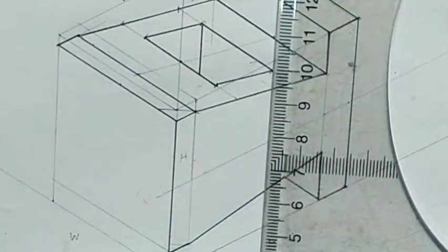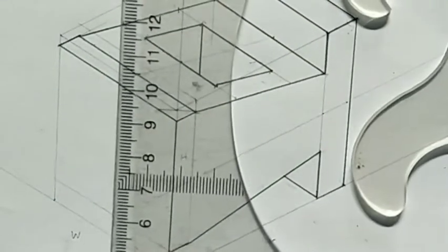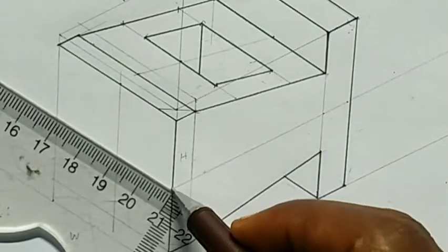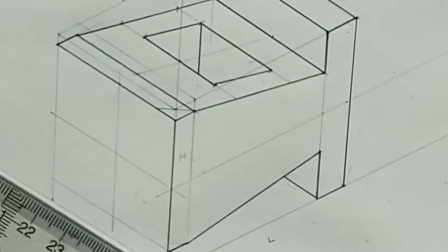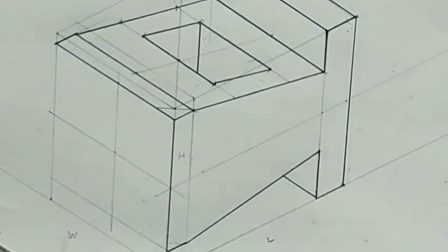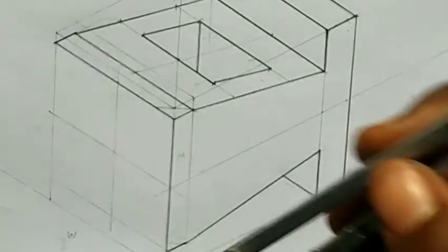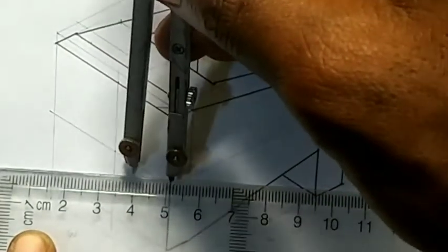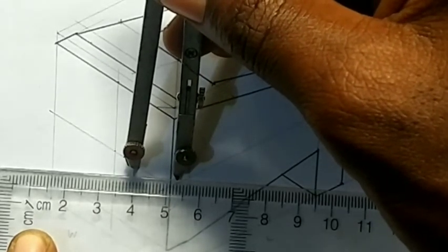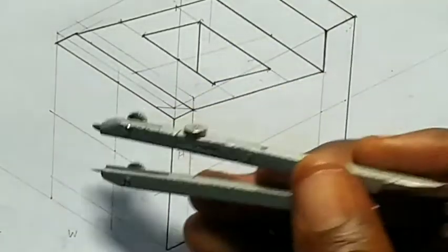So what I will do is I'm going to get the center of this figure. I'm going to roll it this way. Then the other center is there also. I'm going to roll it this way. Where is the center? So I've gotten the two centers, which is this here. And you see diameter is 25, so I need 12.5. And I know very well that this is 12.5. I'll measure 12.5 from this point here. This is my 12.5. So I'll place it at this point.